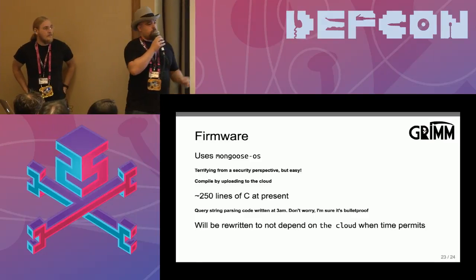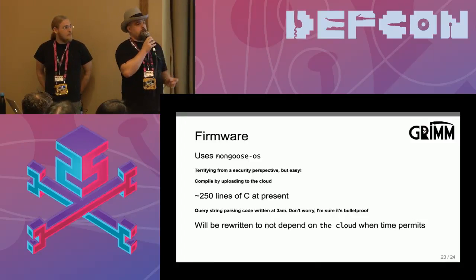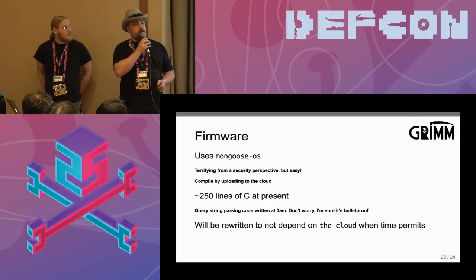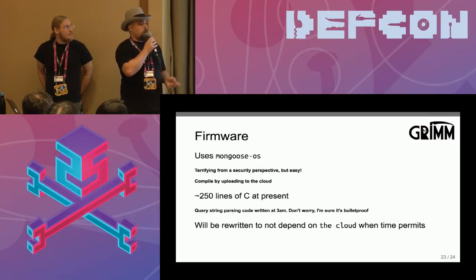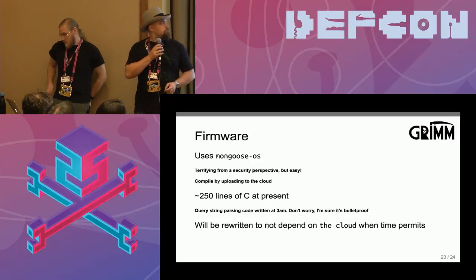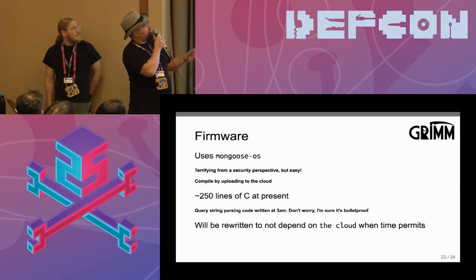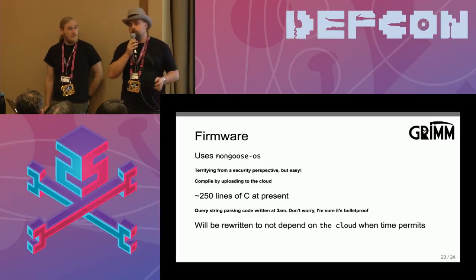You need a 5 volt power source too, there's usually a voltage regulator on the ESP32 dev board to step down from 5 to 3 volts to power the micro. Wire, and possibly a soldering iron. Yeah, and the total cost of all this, assuming you already have a soldering iron and a power source, is less than $10.